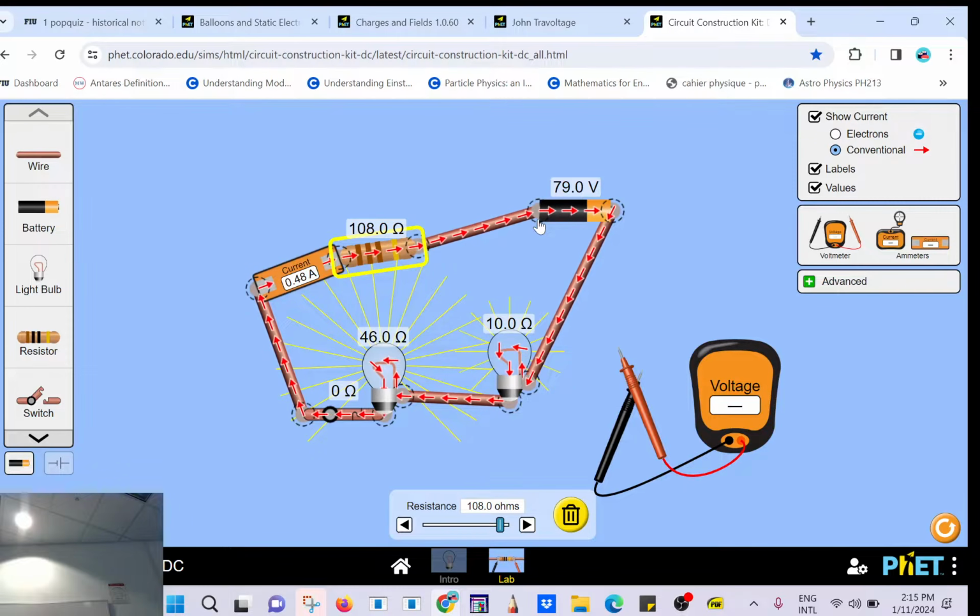So to measure the current, I need to open the circuit, and I have this old device. This is analog. So nowadays we use something like this, which is a multimeter. It's very cheap, but that's the old way. It's analog, but that way you can see what's going on. If I have to go to minus, so this one has to be connected to minus here. It says minus. Okay, you see nothing happens because I didn't close the circuit. So I close the circuit.